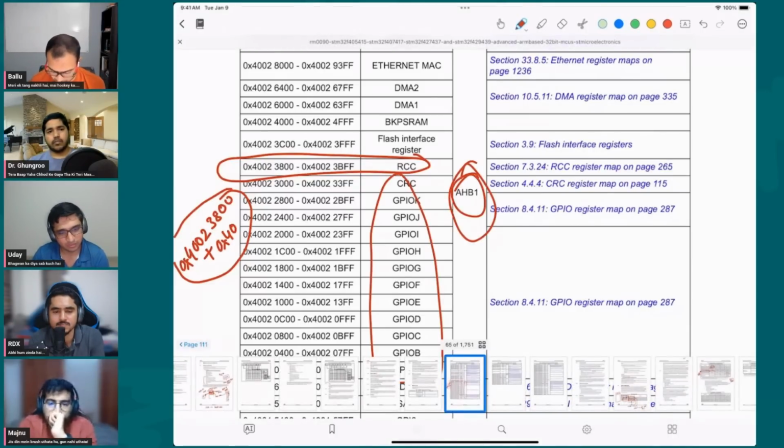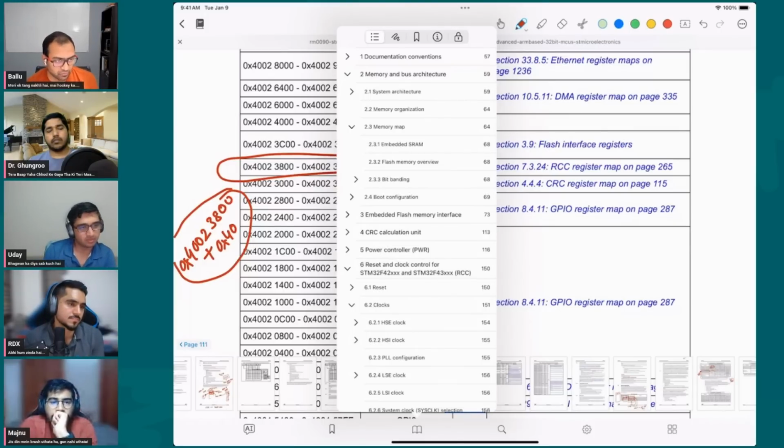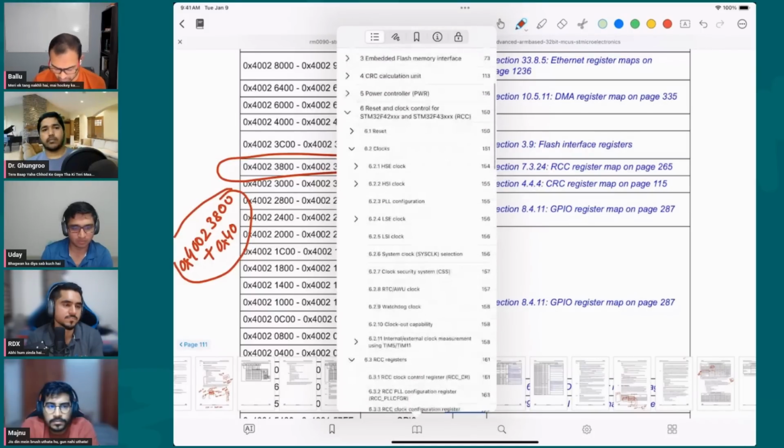So we now know from this data sheet which processor, and then outside of this sheet we had some knowledge of how the CPU boots, which we'll come to in another podcast maybe. Then we figured the base address where we need to put our vector table, so to speak, the stack pointer and the boot address. Then we went about figuring out the clock that our peripheral would need, and we found out that it's on the AHB bus and then the GPIO.